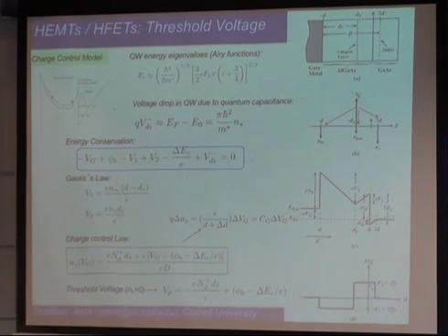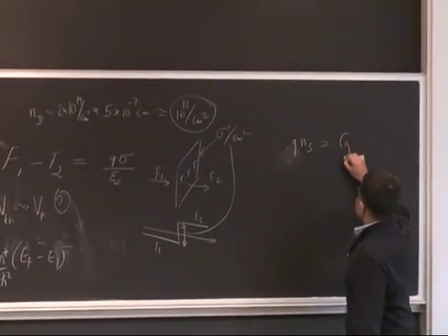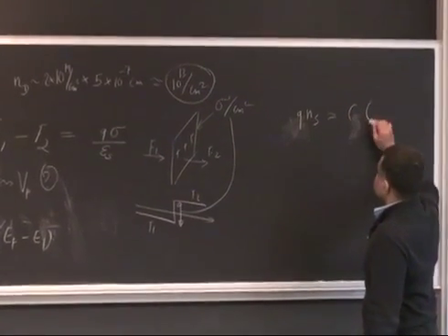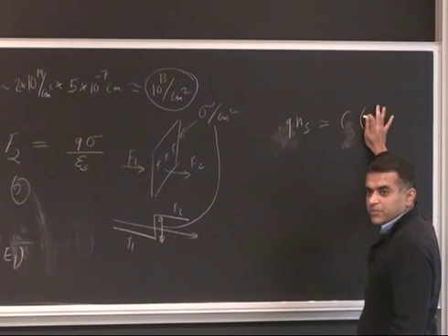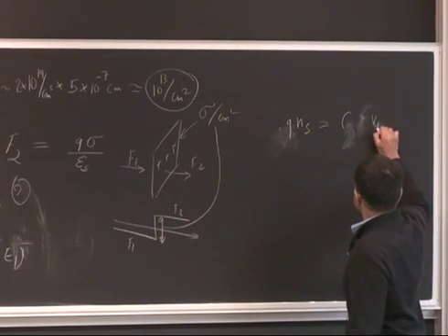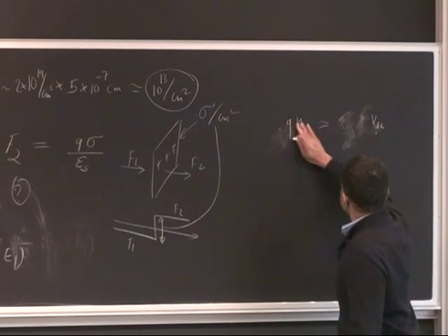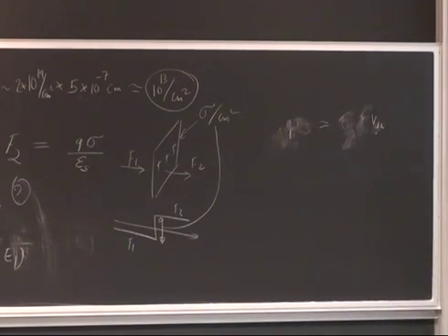Now the simplest way to look at it is there's obviously the voltage divided by a capacitance, or rather, if you want to deplete this much charge, you will always be depleting with some sort of a capacitance times the gate voltage, right? You'll be depleting because you're applying voltage, you're capacitively coupled to it. So if you look at this relation, the threshold voltage will be, on the right side, there will be a 1 over capacitance. Capacitance times voltage is charge.